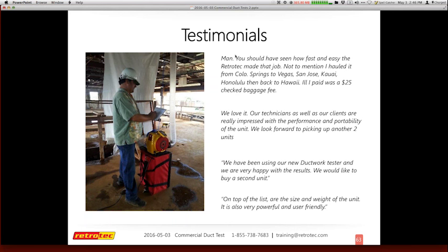Select the duct testing standard. In this case, we've selected SMACNA, but you'll see we've got the European EN 12237, the French standard, residential duct testing standards, and the UK standard. There's also an older version of the SMACNA in there, for those of you that haven't got the new copy of the standard, if you wanted to compare. So that's how you get there.